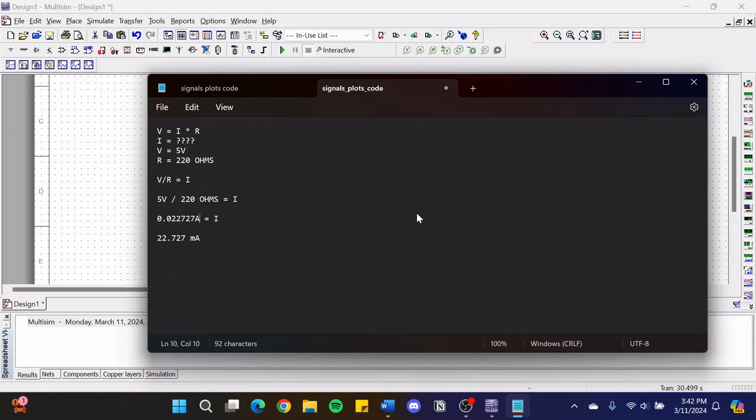So see how here I have amps with a capital A, but this m isn't capitalized. You don't capitalize the multiplier. So the multiplier of the unit, you don't capitalize that. You only capitalize the unit itself. So these are milliamps. Together it's 1 unit. However, milli is just the multiplier of the amps. So the m stays small, the A goes big.